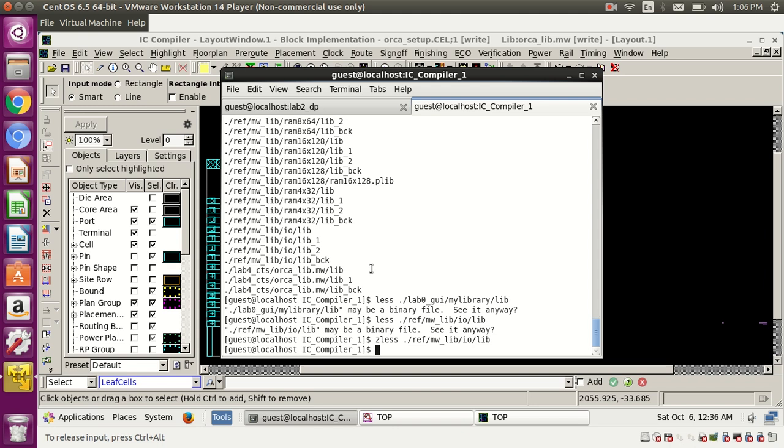The tool has been programmed such that it will group the flops, group the data paths, and check which data paths are stable for some time, even when random inputs change. That doesn't impact the data path. Why? Even if we change the inputs, the data path should change, like all the outputs of the gate should change. Then why is it not changing? I'm saying even if inputs change, the data path may remain the same value. There only we'll add the clock gating for all those corresponding flops.